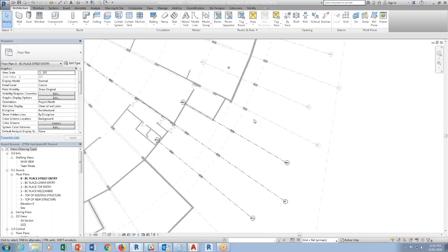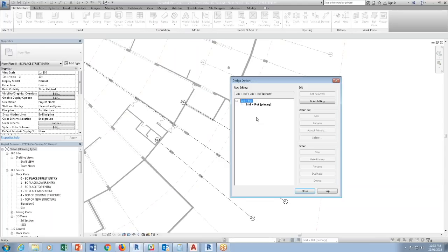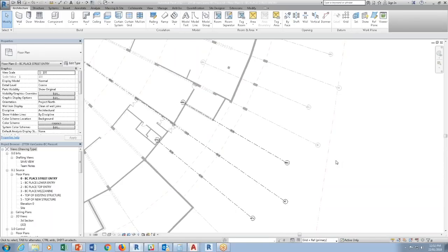Isn't it possible to have a work set setting that doesn't allow it to be edited? No. That's the unfortunate thing. You cannot say, lock things down. No, you cannot, unfortunately. All right. So if you have a link model, this is a perfect example. You could just take a link model and just say put it into that workset lockdown, right? So that nobody should be touching it. Because there's a chance that people will touch it and then will move it. It does happen. So this is preventing people from accidentally moving stuff. Just as an option for you guys, right? So if you want to lock certain things down, prevent people from moving, this is the way to go.